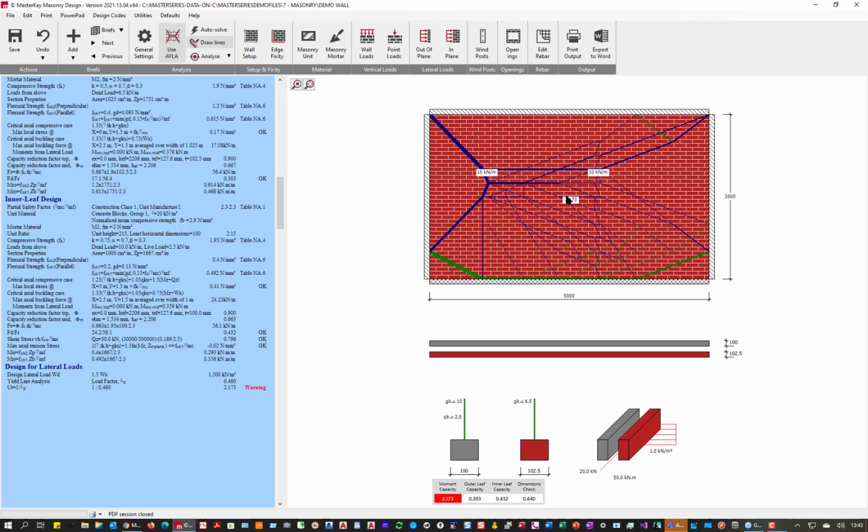So yes, we can put lateral loads onto the wall, point loads, just by using a wee bit of ingenuity, because in reality no point load is going to be a point, it's going to be some sort of finite length, and 100 mil is as good as any with regard to brickwork, because a brick's never shorter than the 100 mil anyway.